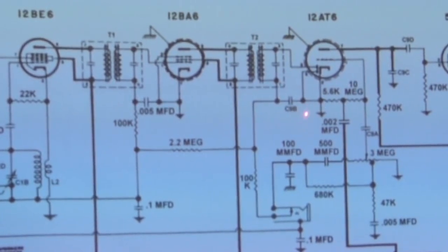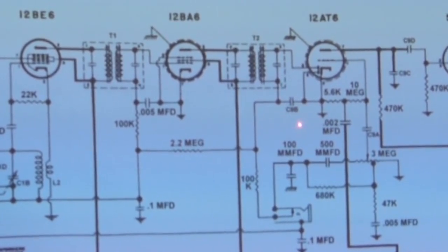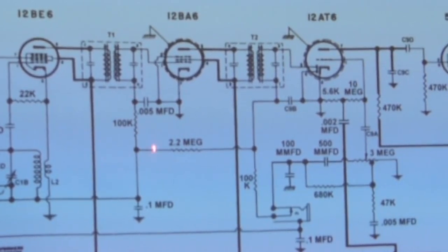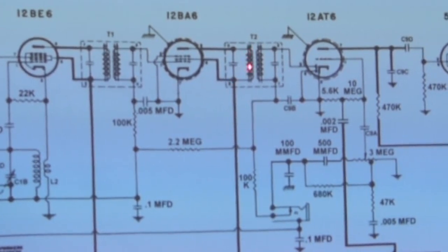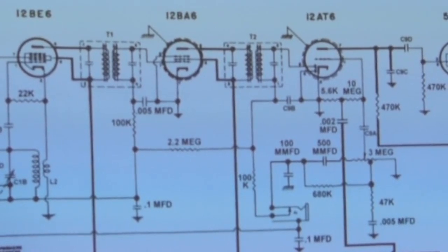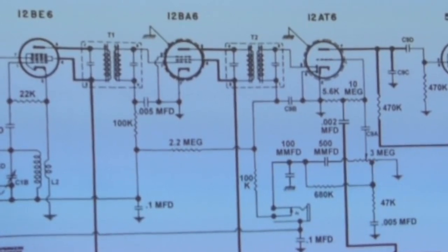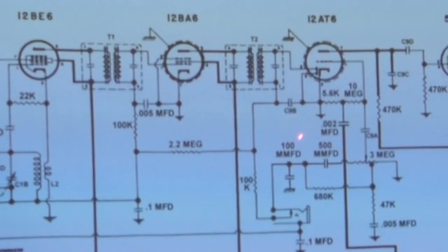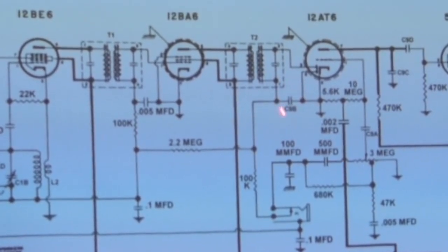You know what we found? Was that somebody had substituted the 100 picofarad cap here for one that was 500 and some picofarads. And what it was doing, it wasn't shorting out all of the audio, it was only shorting out the high frequency portion of the audio spectrum. And so it was garbling the signal. So somebody had changed the circuit previously, and a problem with a lot of antique or old radios is that people have had their hand on them over the years. All right, so when that was replaced, that restored the operation and you got decent audio.